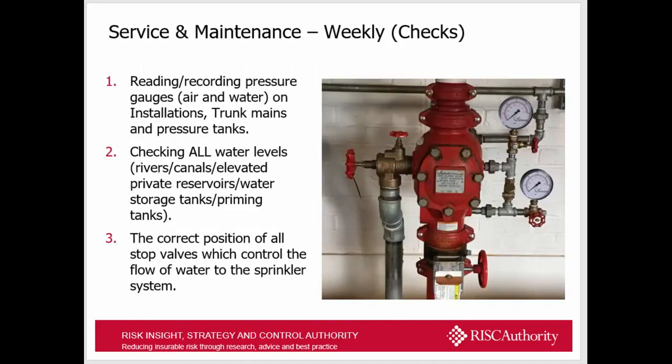So moving on, the weekly checks. I'll now run through the required service and maintenance activities that need to be undertaken to meet compliance with TB 203. And as can be seen there, we have a standard valve set on the right hand side. So what should be done on a weekly basis? These are just checks. So recording that there is pressure on the system. Looking at the gauges there on that particular picture, there is no pressure in the system, so the system is isolated. As you can see, the valve at the bottom is shut.